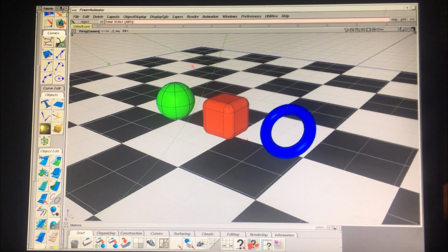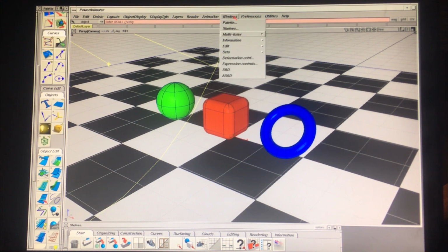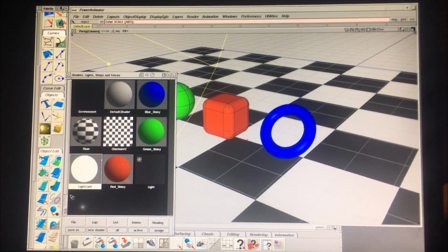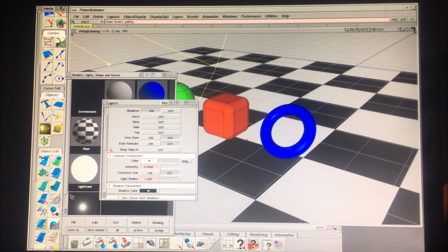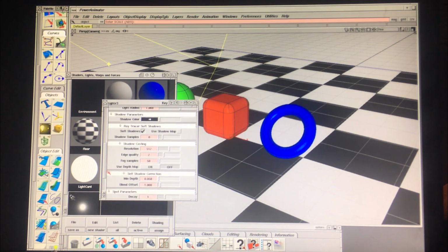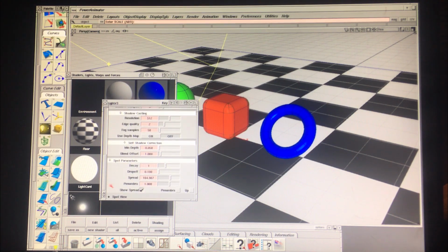Now, we didn't have enough samples on the light, so I'm going to go here. We'll go back to the Windows multi-list or list all. I'll go back to the spotlight. I'll turn that intensity down to 8 since it was pretty bright. I didn't see the edge of the penumbra, so I'm actually going to bring the light in a little bit here. On the spread, I'm going to bring it back to like 88. Maybe we'll get some fall off in the middle here.